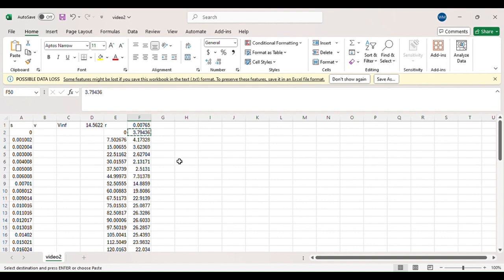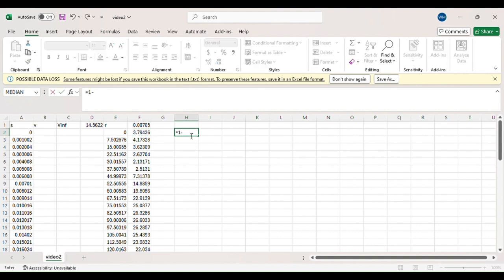So to generate coefficient of pressure, what we will do is utilize the fact that we simulated inviscid flow to simplify the equation for coefficient of pressure to equal 1 minus measured velocity divided by test section velocity, whole square.